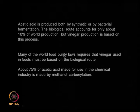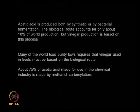Most of the world food purity laws require that vinegar that is made for food application must be based on the biological route. So that means if you want to make PET, the acetic acid can be made through the chemical route, but if you are interested in manufacturing vinegar, then the acetic acid has to be manufactured using biological methods. Most of the acetic acid in the chemical route is based on methanol carbonylation. So it is a homogeneous process using methanol as the raw material, and it is a carbonylation reaction. So the carbon monoxide is put inside methanol to make the acetic acid.